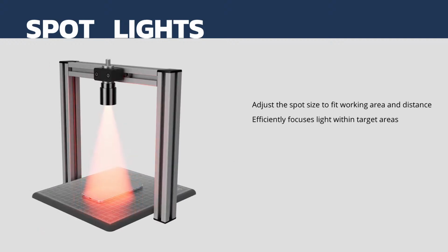It's also notable that on things like the spotlight, we have the same SXA30 spotlights as the fixed ones I talked about where you order it with lensing, but with the A is adjustable, and SXA30 then has a zoom lens that goes from 1/2x to 5x in its spot size, and so you can mount this, and just like you see in the diagram, by screwing the lens in and out, we can get a bigger and smaller spot. Again, think of the actor on the stage and zooming the spotlight in or out to cover the whole stage or just the actor.